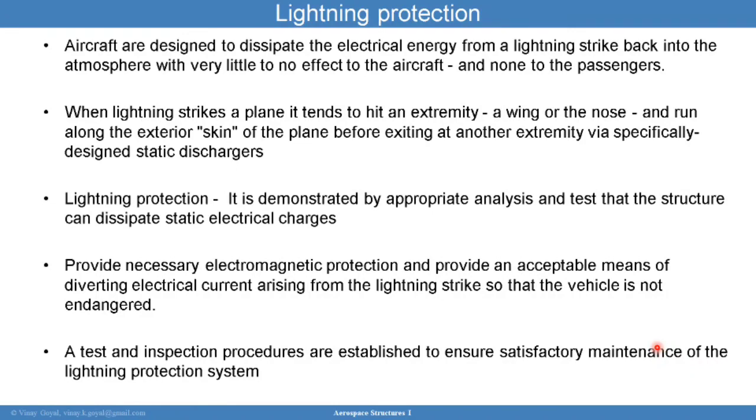Aircraft has also incorporated lightning protection, and they show by analysis and tests that the structure can dissipate the static electrical discharges, and they also provide necessary electromagnetic protection and provide acceptable means of diverting electrical current arising from lightning strike so that the vehicle is not endangered.